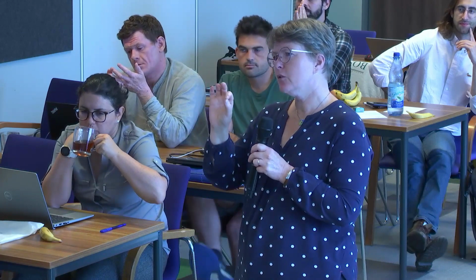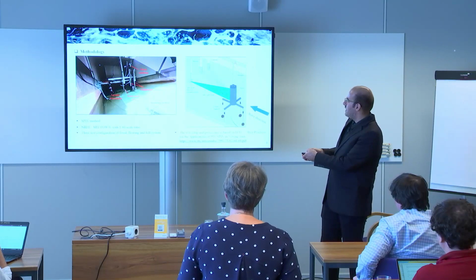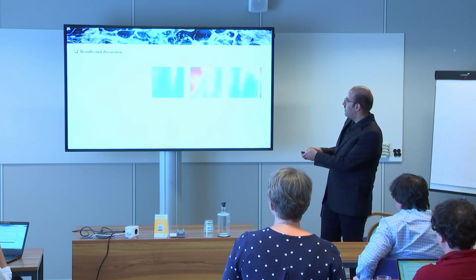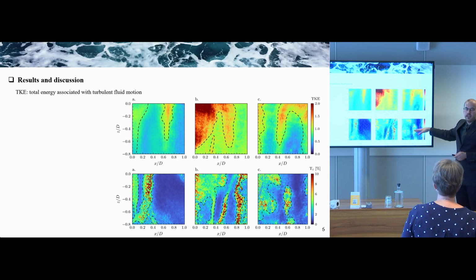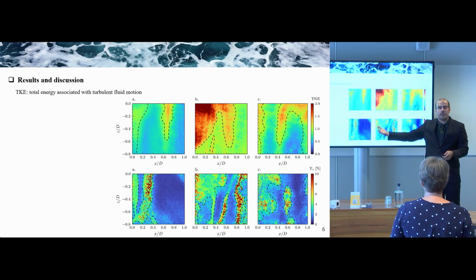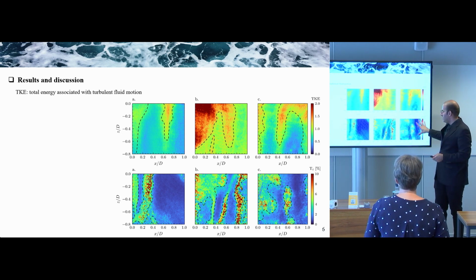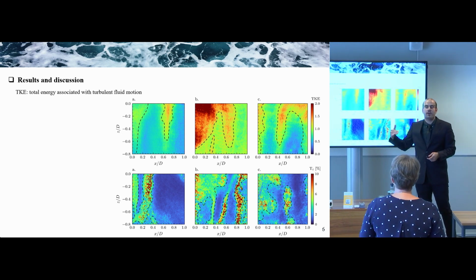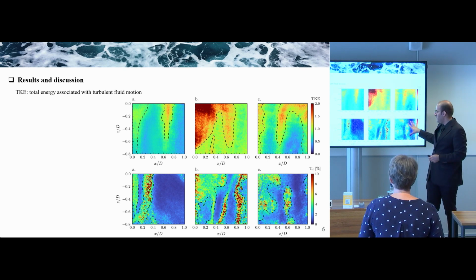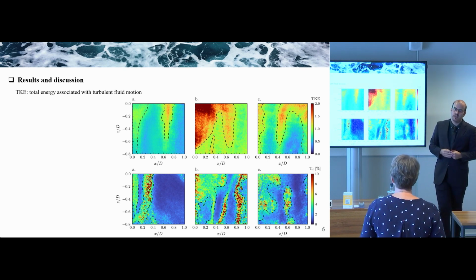Because I found that the Reynolds stress tensor images were still quite scattered. I was expecting that with, I don't know, 10,000 images or something like that, you would have something smoother. Well, the point about the Reynolds tensor here, or even about the TKE and TI, is that we have an irregular incoming wave. And this is the time average of the result of the irregular waves. If it was regular, it would be neater.